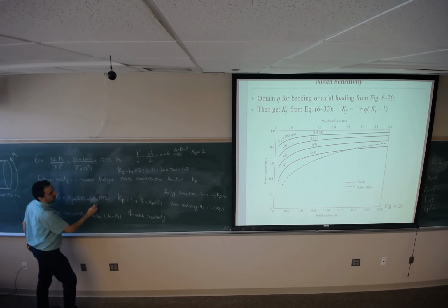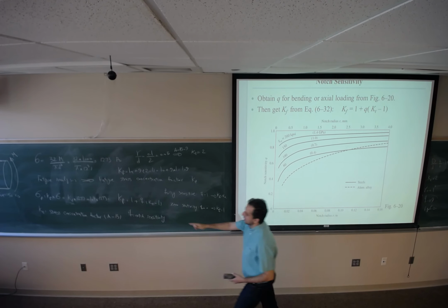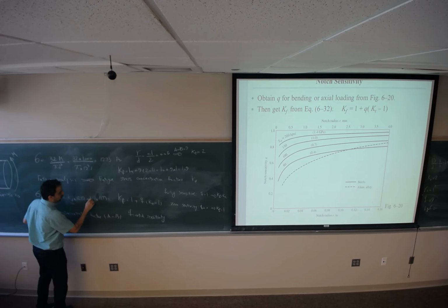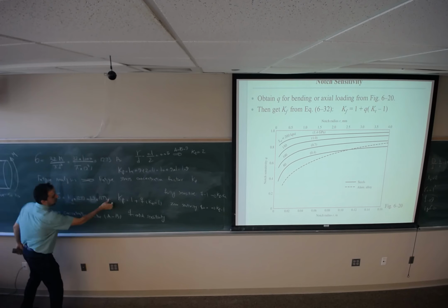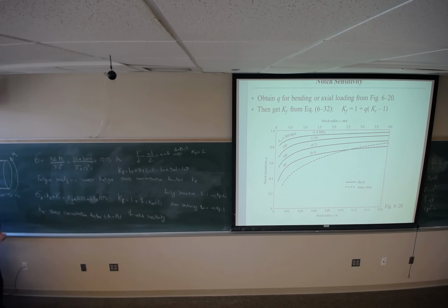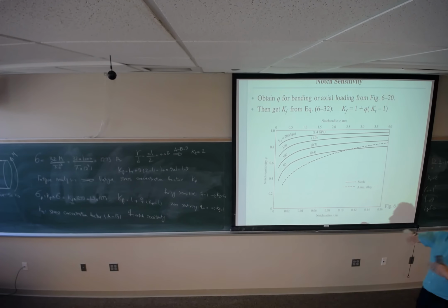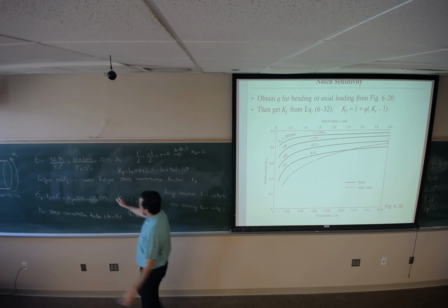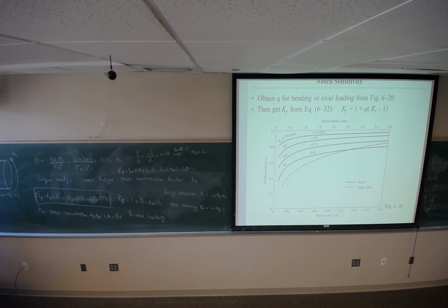It's going to increase the stress by about a factor of 2. So if you did your design based on this stress, then you are going to see failure if the mechanical component is rotated, because the fatigue concentration factor is going to increase the stress, then you have a fatigue issue. Can you see that?